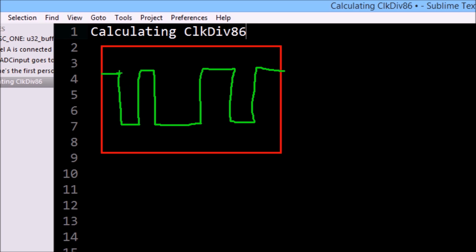So I kind of want it to look like that, with the start bit, data bits, and stop bit. So that's one reason why I start at address 100 on the counter module, and then I only want to sample this waveform fast enough where I approximately get the end of the stop bit at address 700. Because if I sample too slow, then the waveform is going to be really tight and condensed, because it's just going to appear as a short amount of time. And if I'm too fast, then the waveform is going to be stretched out, and then I might miss a component of the waveform. So it's important to figure out the correct sampling rate at which I want to grab this data, so that it fits nicely on the VGA monitor.